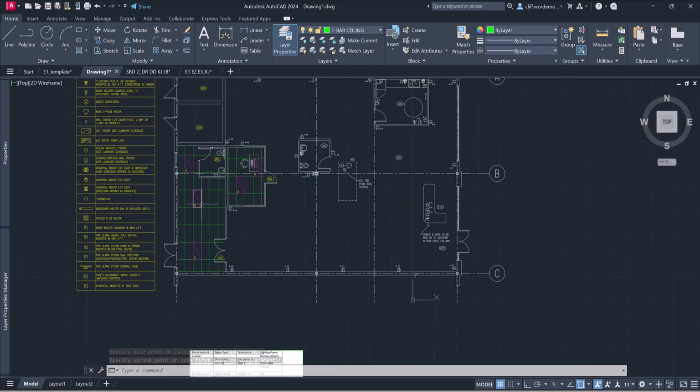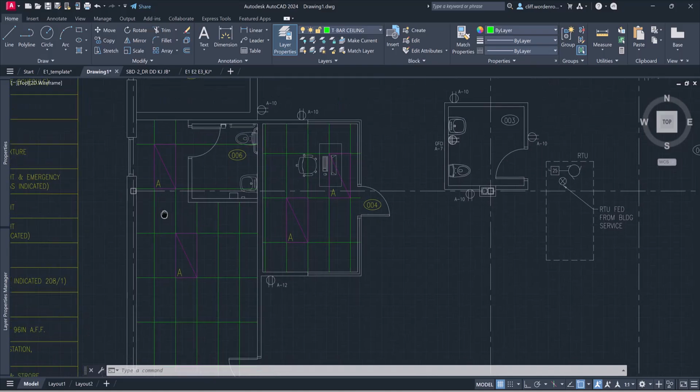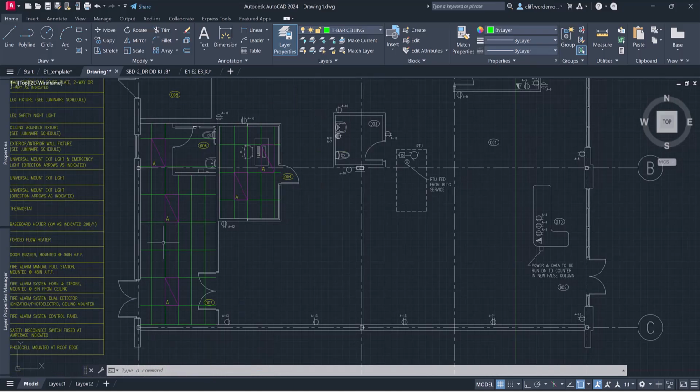This one, again, it could come a little bit further down. We could shift the tiles over slightly, but when you walk into a room, you get a light. Again, this is all lit area. Really, I was surprised it only gave us 3 lamps. We could probably, if we lower the lumens a little bit, get 4 lamps in here. Well, maybe that's it. Yeah, it's just because there's a 2 tile spacing.